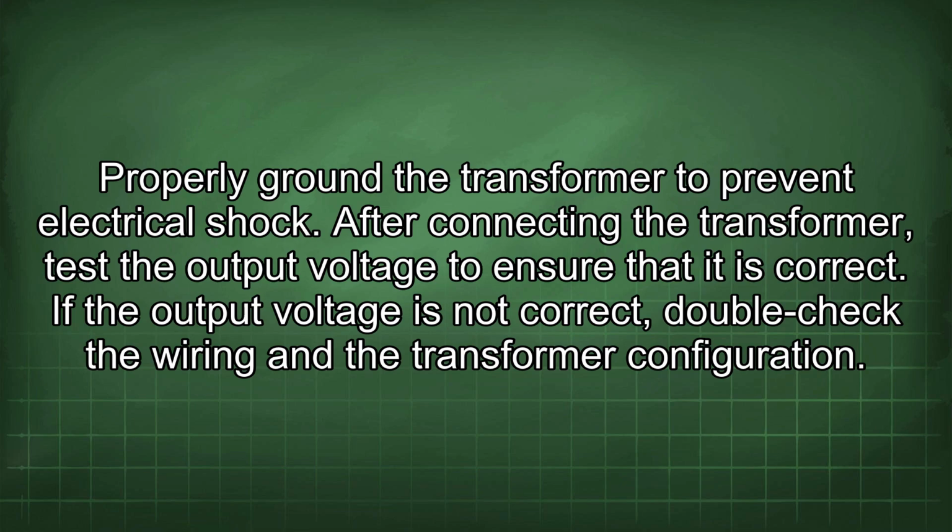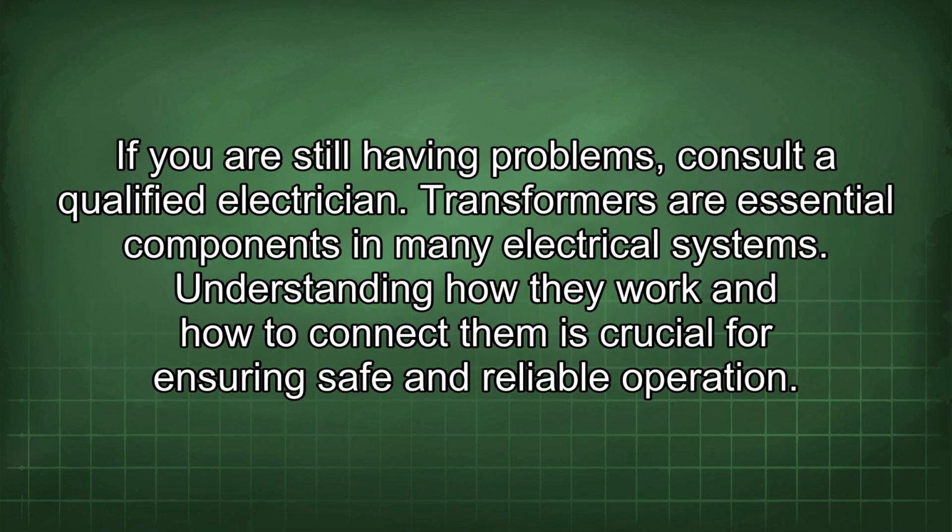After connecting the transformer, test the output voltage to ensure that it is correct. If the output voltage is not correct, double-check the wiring and the transformer configuration. If you are still having problems, consult a qualified electrician.